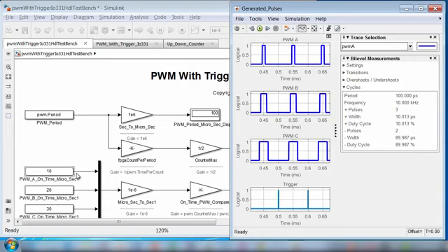I was commanding, as you see in my system model, 10 microseconds, and that's what I got. 10 microseconds. It's a smidge off because I do have some integer math going on inside of the PWM algorithm, so I have a bit of rounding. Also notice that I have a 10 kilohertz period. That's the frequency, and so that's also per my spec, so I'm happy with that. If I want to go down here and check PWM-B, for example, I'm getting 20 microseconds, and that's what I asked for. You can see here 20, and then if I check PWM-C, I'm expecting 30, and that's in fact what I get. So good. At this point, I have a functional design. It's behaving the way I specified.